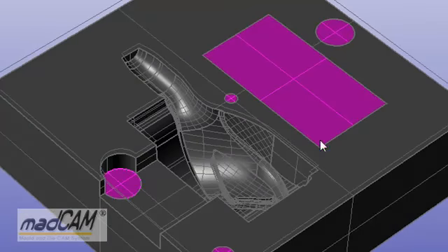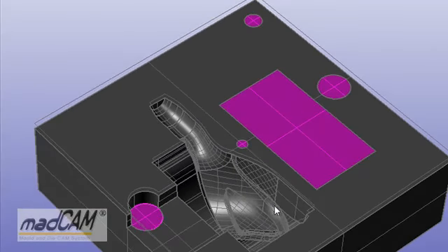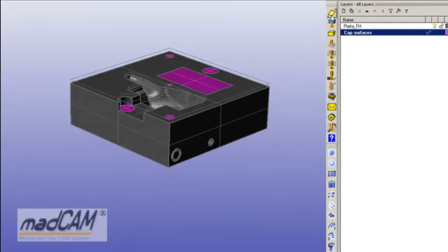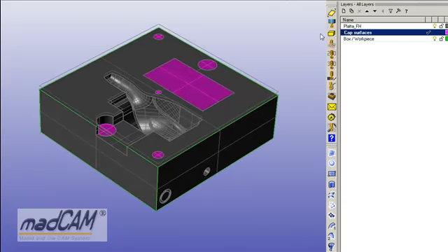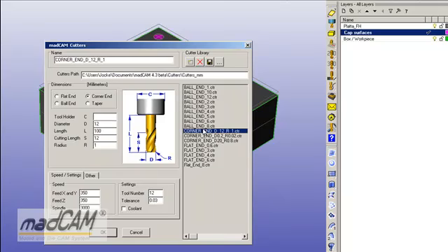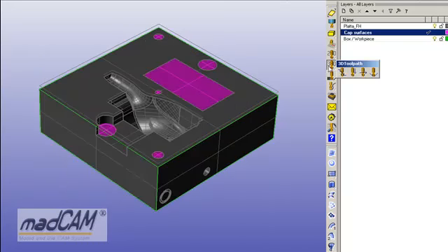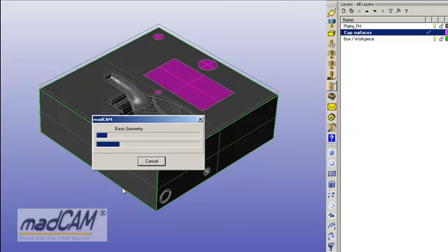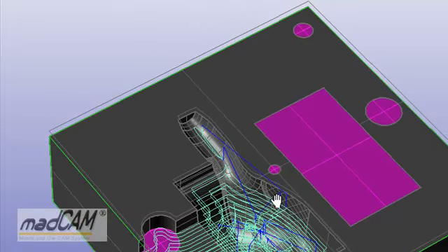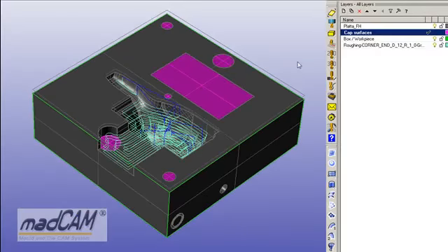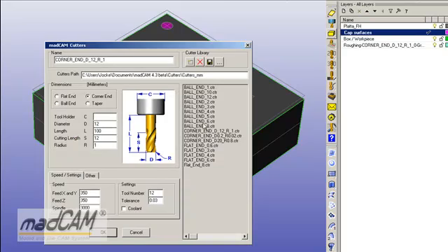And now we have created a couple of cap surfaces to prevent the cutter from machining some areas on the model. Then it's just to reselect the model including the cap surfaces, and we can create a new roughing toolpath. And now we can see it will not machine down in those areas where we have the cap surfaces. So now we can continue creating a finishing.